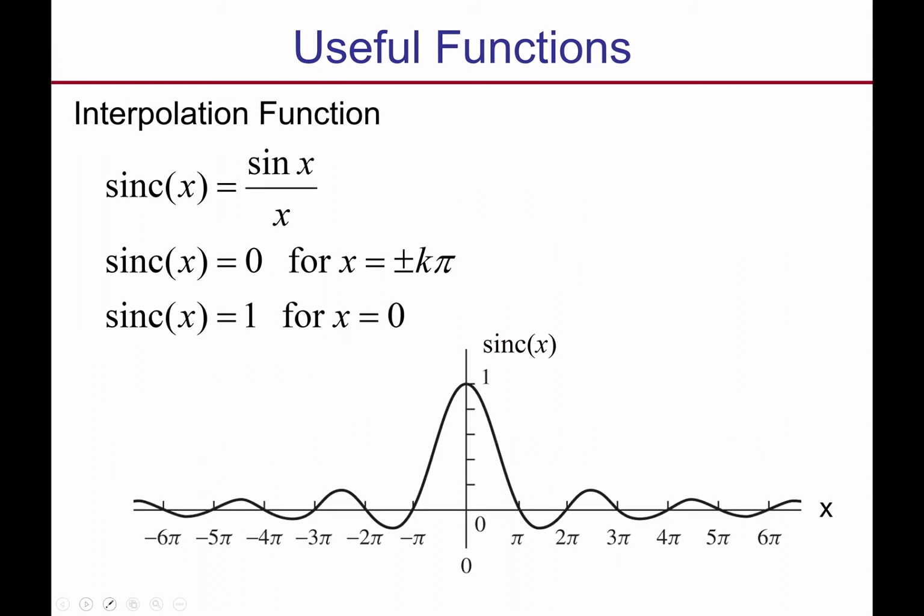The next important function is the sinc function, or sometimes they call it the interpolation function. They call it interpolation because if you have a signal like this and you have samples of the signal, in linear interpolation you will just connect lines between them. But if we use sinc interpolation, which is more powerful, at that amplitude, a sinc function here, at this amplitude, a sinc function here, a sinc here, a sinc here. And if I add all these sinc components, I will get perfectly the original signal with no approximation, and that's why they call it interpolation.